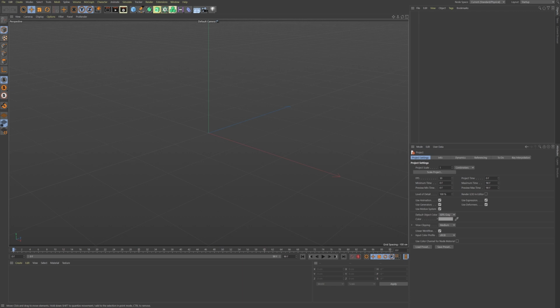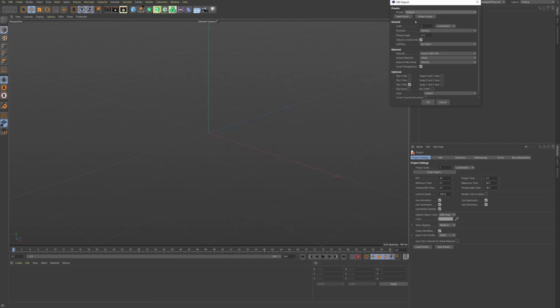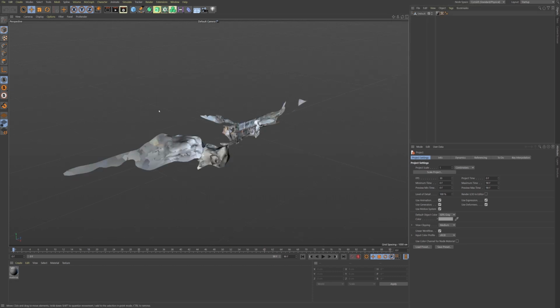First, we want to bring in our 3D object. And you can simply do this by clicking your OBJ file and dragging it into your scene. From experience, I can advise you to change this value from 1 to 100. This means that you are actually changing the unit from centimeters to meters. So, choose 1 meter or 100 centimeters and press OK.